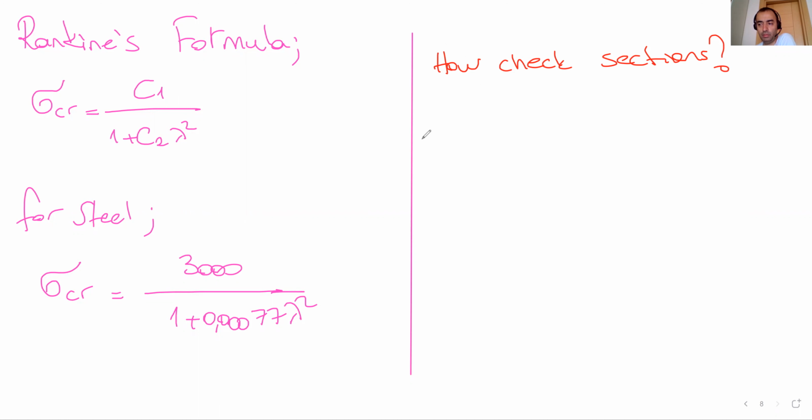If we know the LK, the buckling length, and then the minimum radius of gyration. Why we are dealing with minimum, I will explain. Calculate I minimum: check the moment of inertia for both axes and take the minimum one, over A.